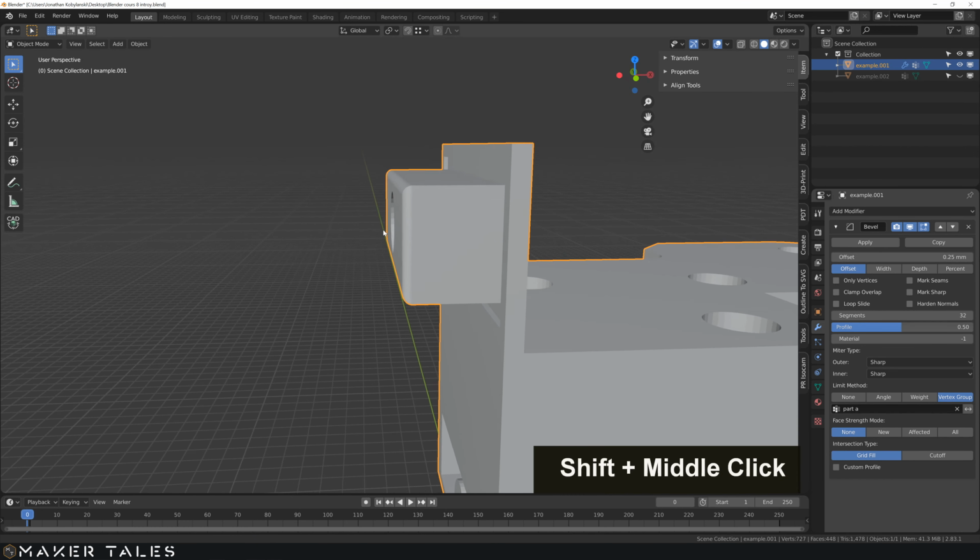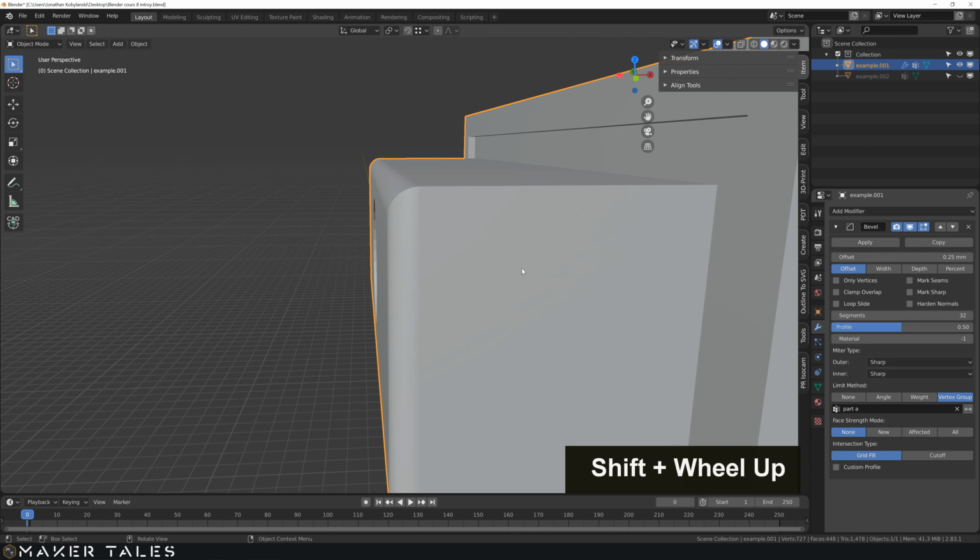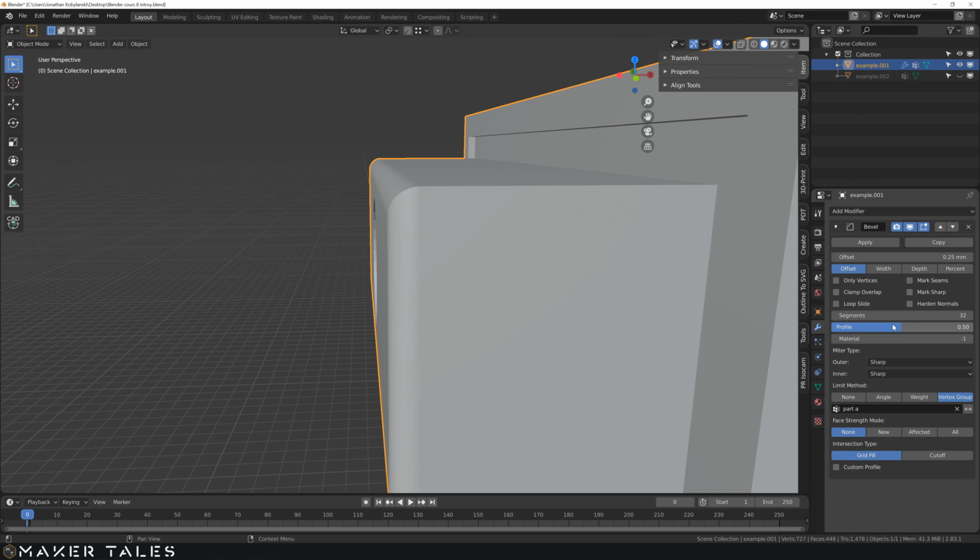And then lastly, let me just show you that the bevel modifier has this thing here of segments, so we can segment how refined this bevel will be. We also have this, which is our profile. Because we're doing precision modeling here, we're going to always have this set to 0.5, but I want to show you that you can go concave here, and you can also have it more rounded in this sense as well. So there you go, just so you get a sense for it.